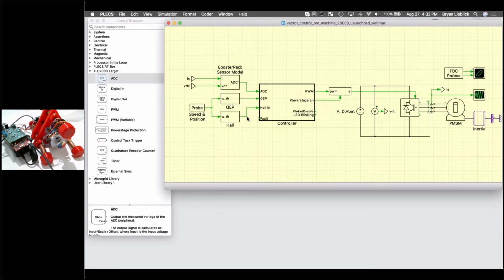electrical degrees. A quadrature encoder has finer resolution on the rotor position, but an index pulse is needed to detect the absolute position. And that index pulse is triggered only once per mechanical revolution. And so before that pulse is triggered, for example, during startup conditions, then the Hall sensors provide more accurate position information. So once that index pulse is received, then the QEP has better resolution for the rotor position.